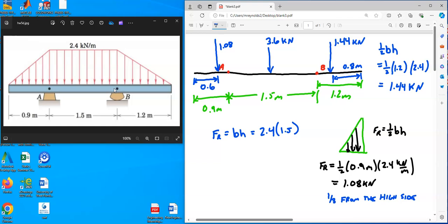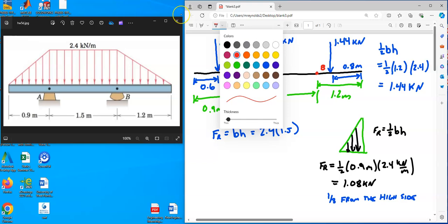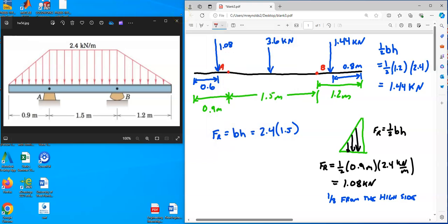Well, I tried to state in the problem, the reaction forces, I'll draw them in red. The reaction forces are going to look like this. There's going to be a reaction force FA that goes up at A, and a reaction force here, FB, that goes up at B. This is the base of the bridge, the supports, where they push up on the bridge, because you have to have the same amount up as you do down.